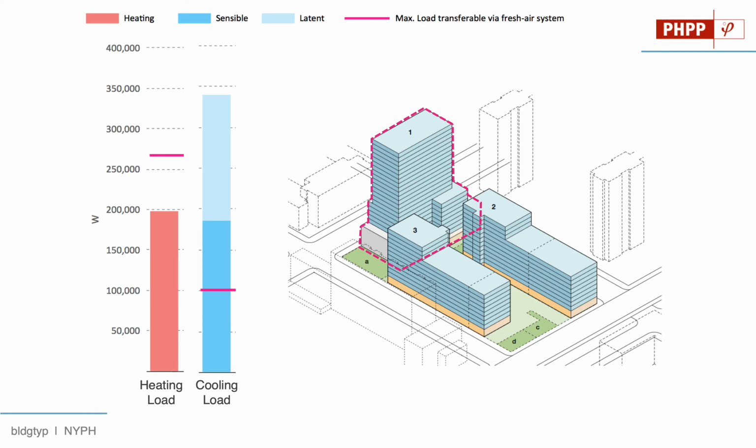And notice that, interestingly, because of the density and the glazing and the insulation on this building, you probably could have done all of the heating supply through the ERV if you could ever figure out how to do controls properly. From a strictly energy in, energy out sense, you probably could have delivered all the heating through the ERV.